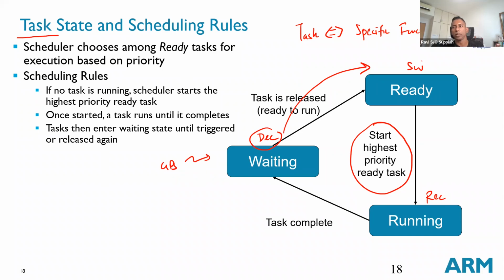So the switch went to the back of the queue and decode took over. The switch is no longer the next in line. The highest priority task is now decode. That is why the moment a record finishes, the decode task will be able to take over the CPU.